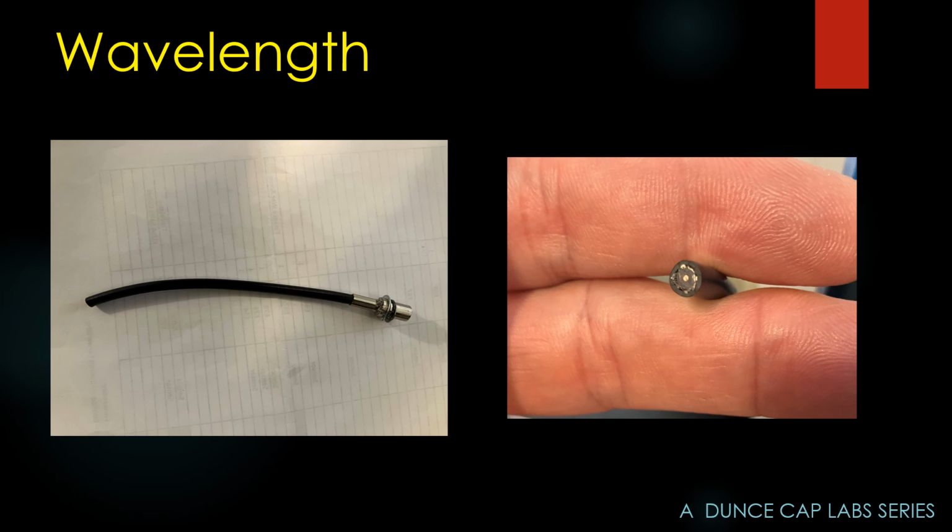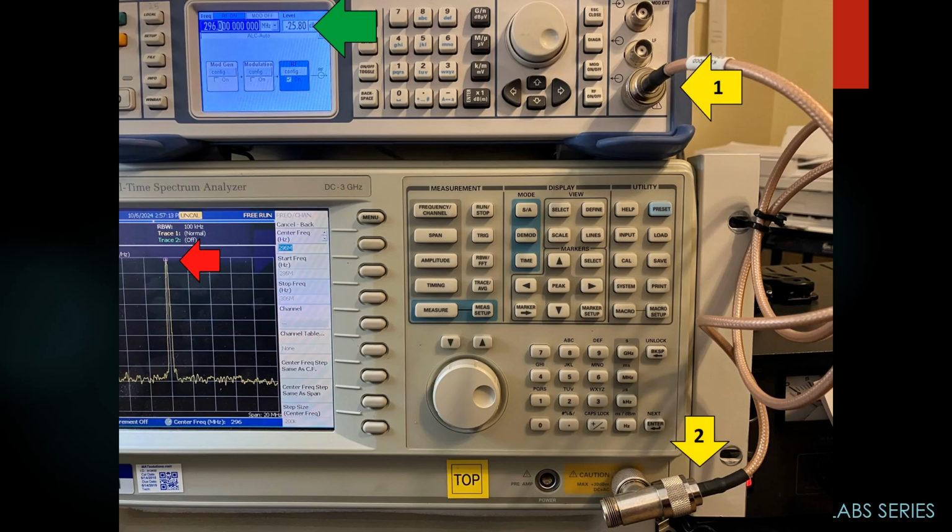So first of all, let's see if I've cut it properly. Here's my test setup. On the top is a signal generator. Notice the green arrow. My output level is minus 25.8 dBm. My output comes out of the coax cable with the number 1 arrow. That coax loops down to the number 2 arrow, and through a T connector goes into my spectrum analyzer. Look at the red arrow.